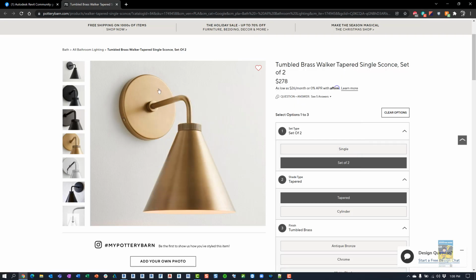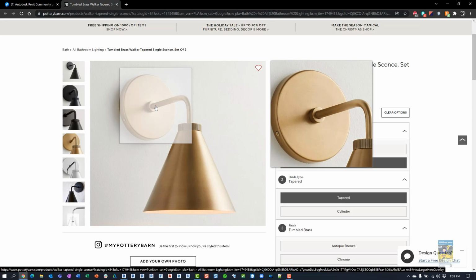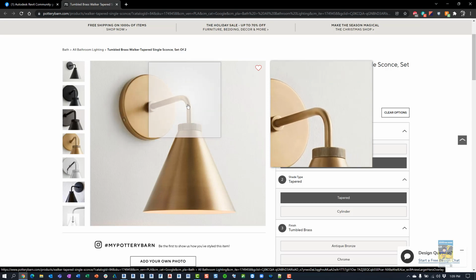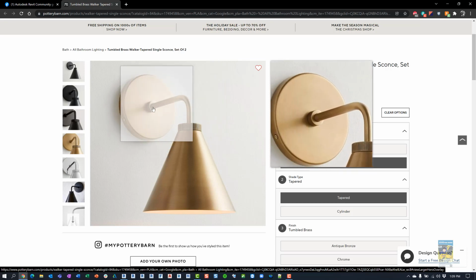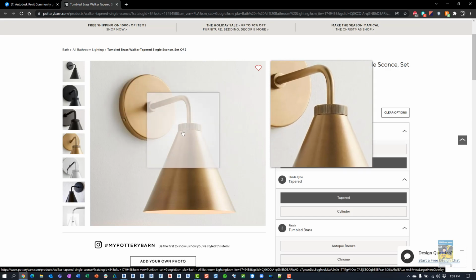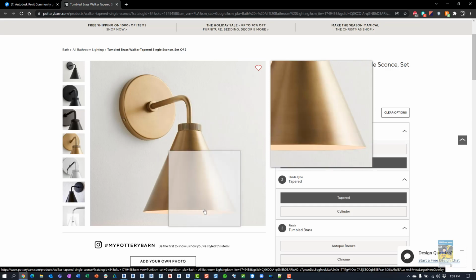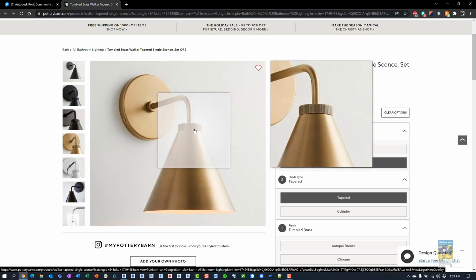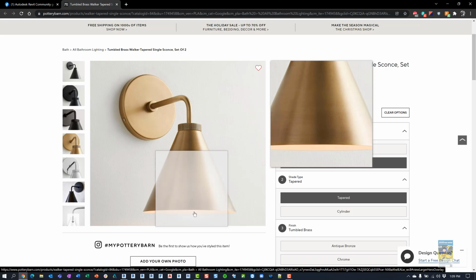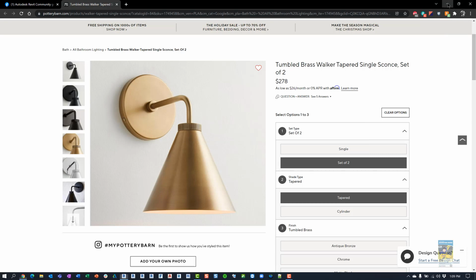This is pretty straightforward in the sense that we have a circle that will be extruded. We have another smaller circle that will be extruded. We'll have a sweep that has a path that looks like this with a circle as a profile. We'll have an extrusion of a circle, and then we'll have a blend going from a smaller circle to a larger circle. Or we can do a revolve, so that way it's empty on the inside, and our light source will be on the inside of that light fixture. So let's go ahead and get started.